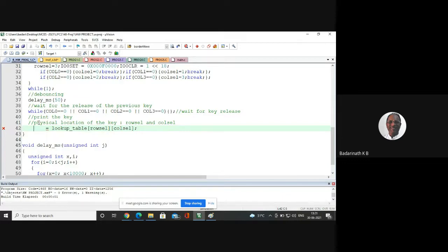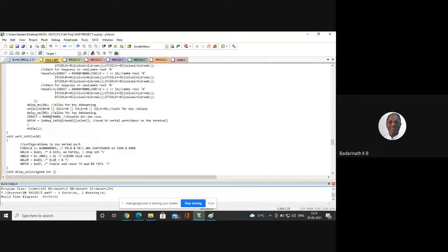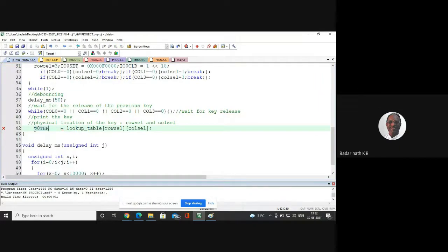Or there is what is called a serial terminal in the LPC2148. The LPC2148 has a UART. That means through that you can send the data to a computer terminal also. Here in the simulator, whatever I push to the UART, I can watch in the serial terminal. Instead of putting it to the port, I can send it to the UART. So I will take the UART method now. I'll take a UART register and copy the value into that register. We will put it to the port also after this.